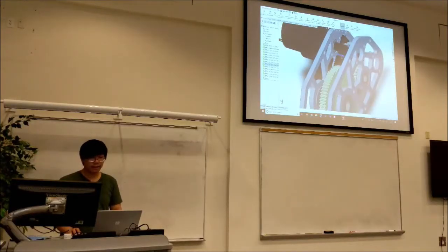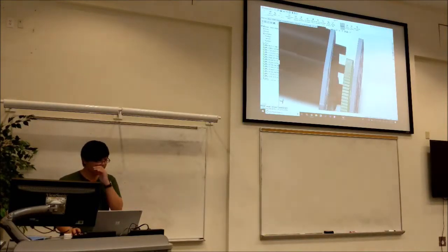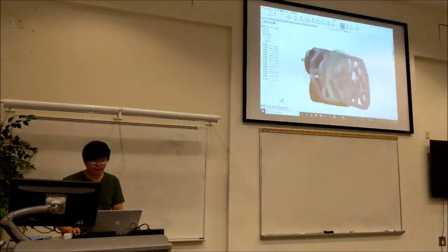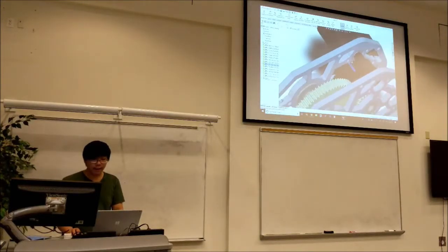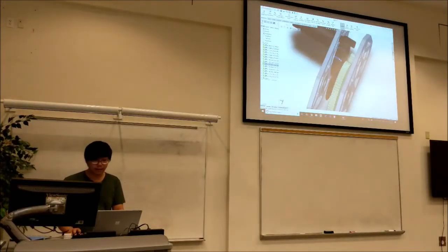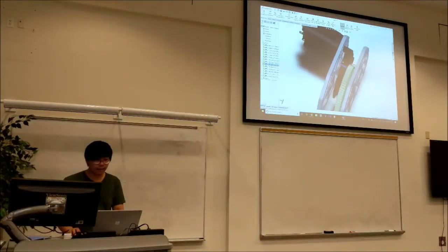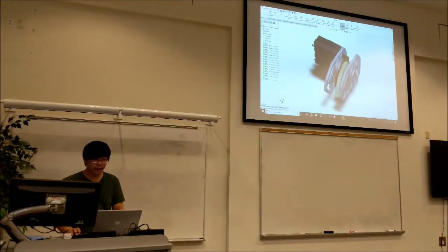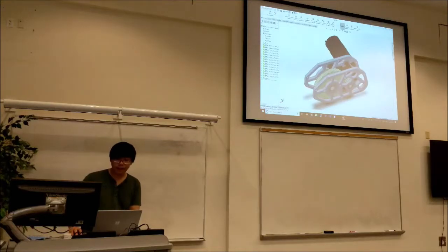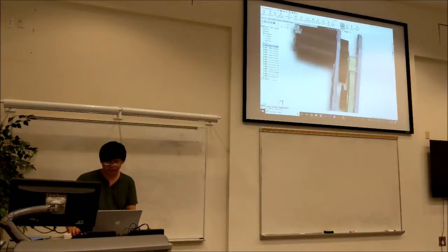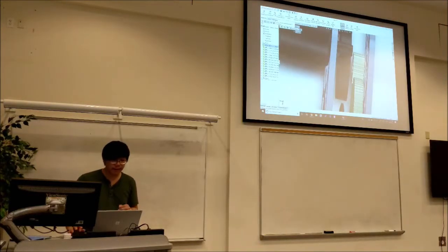And then with this gear, this is something I changed from when I first guided it. When I first guided it, I actually had it up here, but because we're cutting, we can see if this clears everything, and the mounting screw for this motor actually interferes with it. So it's super easy to change, just dimension the gear with some spacing away from this bearing, and it fixes the clearance issue. This is a simple issue to fix, but if it required a redesign, then having your sketch for this plate allows you to really quickly change your bearing spacing and change your gear ratio.